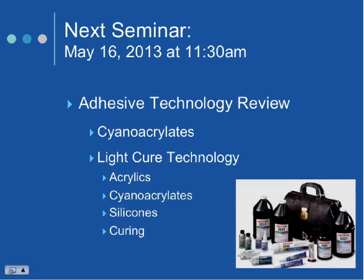You could place it in acetone, but you mentioned polycarbonate. I don't think it's going to do well with acetone. So if you're bonding metal to metal, you can soak in acetone and possibly get it apart, or if it was just a drop or a little bit, you might be able to manage that. But after it's cured, it's pretty much there. So it probably wasn't the answer you wanted, but it's the truth. Any others?